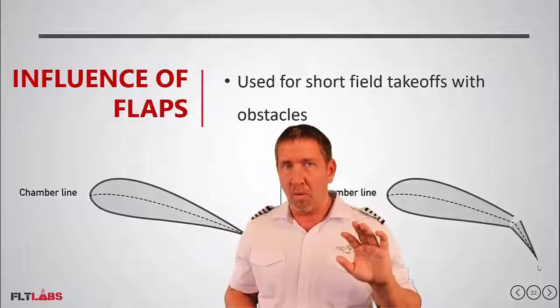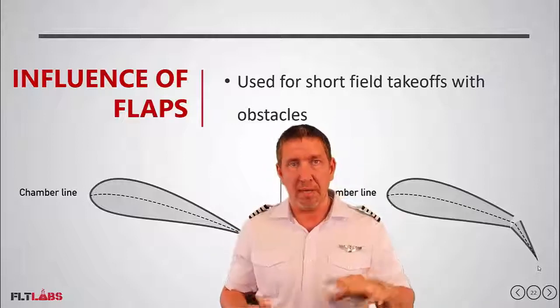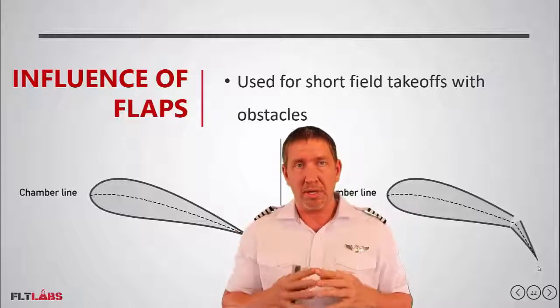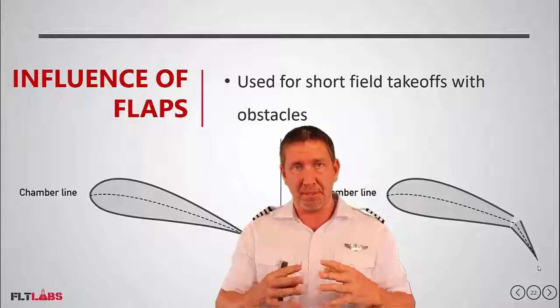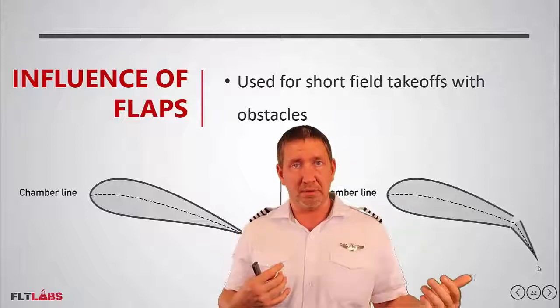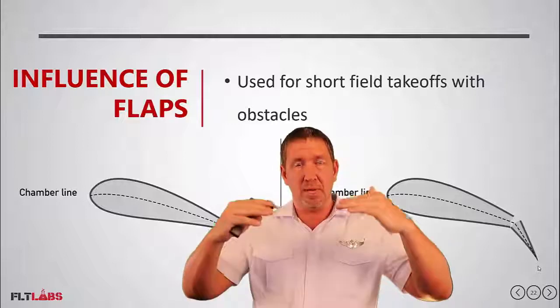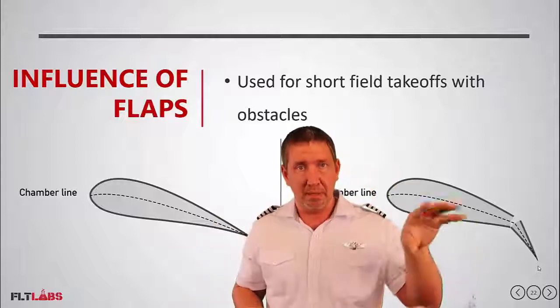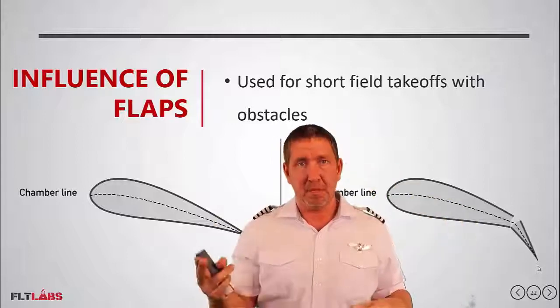All right. A few other things I'm going to talk about in the video that we saw, and we're going to watch that same video again. We're talking about now we take off with flaps in the takeoff position. We get to 300 feet. That's a safe altitude for us to transition to flaps up. So first, we make sure that we have a good speed, okay? Speed checks, flaps up selected.